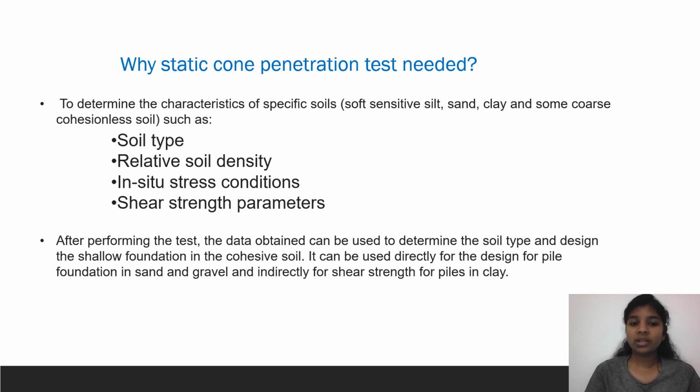After performing the test, the data obtained can be used to determine the soil type and to design shallow foundations in cohesive soil. It can be used directly for designing pile foundations in sand and gravel, and indirectly for the shear strength for piles in clay. For that purpose, we use the static cone penetration test.